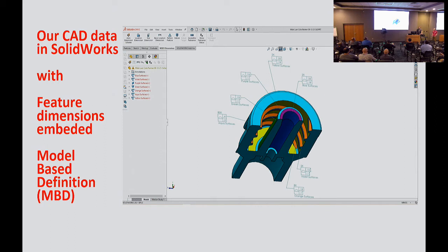And so we use a package called Smart Profile, and there's a new interchange format called QIF, the Quality Information Format. SolidWorks has an export, you know, I want to export as, and QIF is one of the choices, and so it exports the model and all of the GD&T appended to it. So when we start in Smart Profile, we're pretty far down the track.